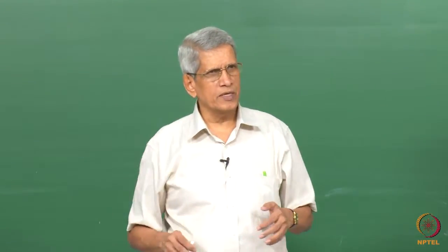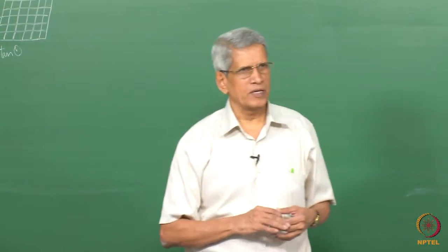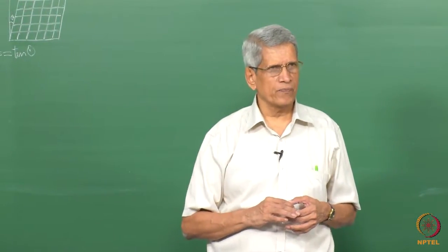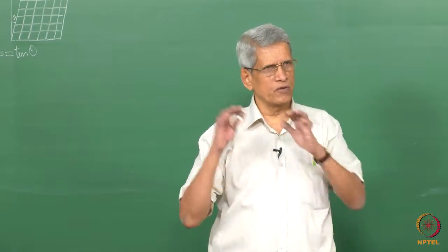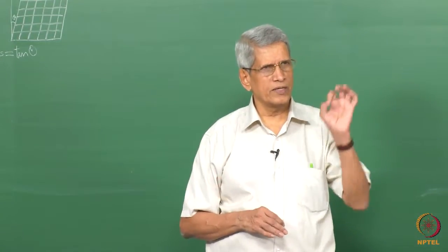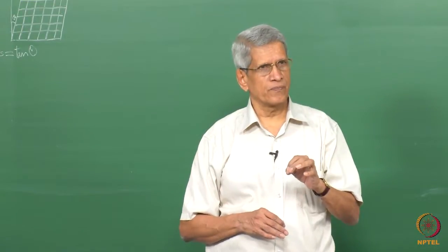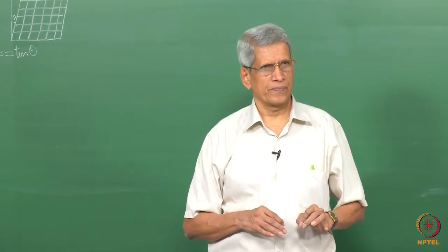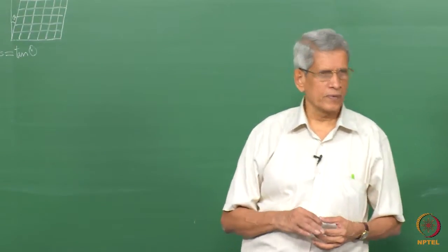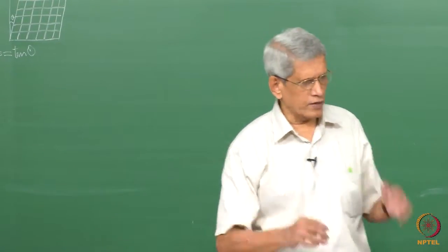So in many materials where slip takes place, at the end of the deformation, when the strain is very high and dislocations find it very difficult to move, in those circumstances twinning can occur. Is it clear? Okay. That is one.